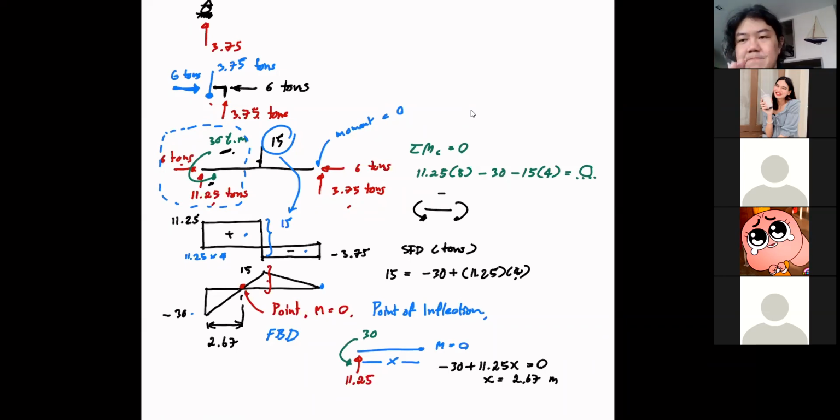So when we face a tougher situation, we want to approximate the behavior of our structure. We can assume where this point is and put a hinge in the structure and then start our approximation from that point. So to have some idea where this point is is very, very useful, I have to say. It's a very good question. So if you can locate that, it would be great. And if the point of inflection exists in your structure and you fail to locate it, you may not get a full score. So it's going to hurt a little bit.